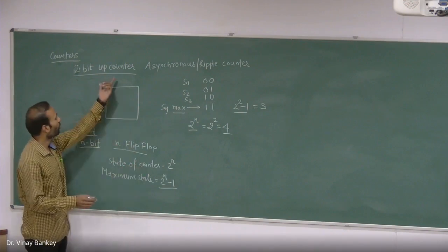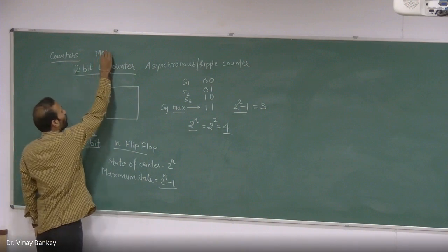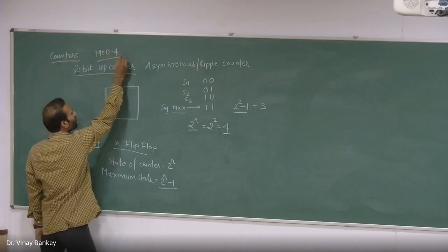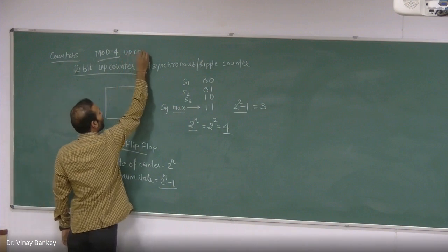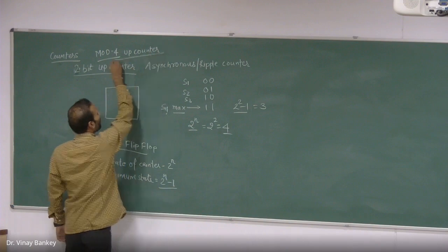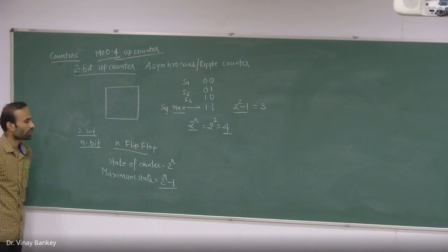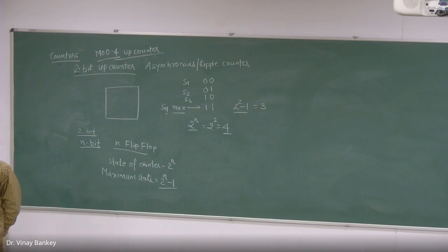So we can also call this counter a mod 4 counter. The total number of counting states is also called the modulus of the counter.